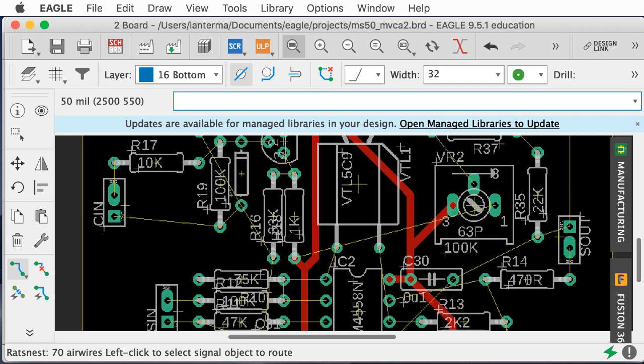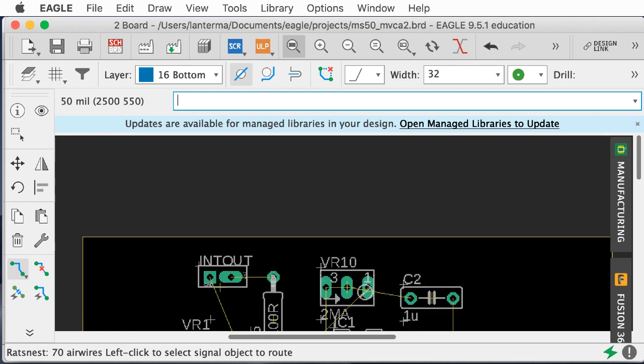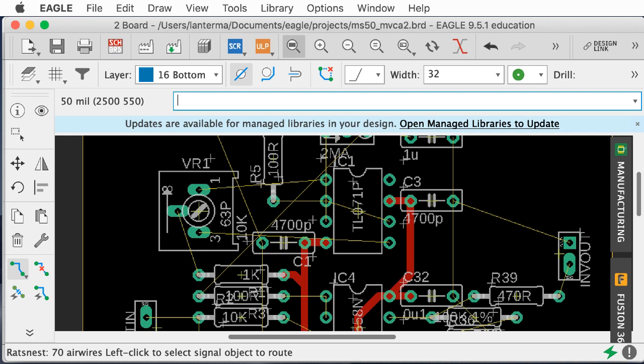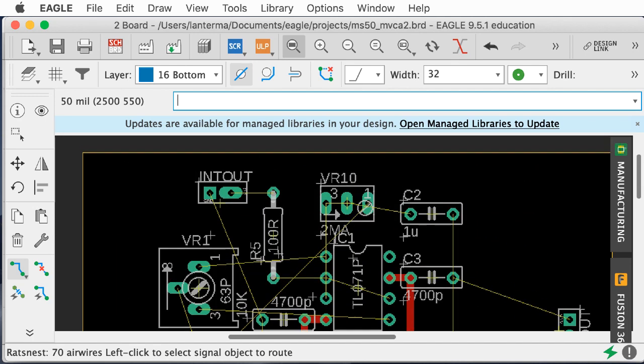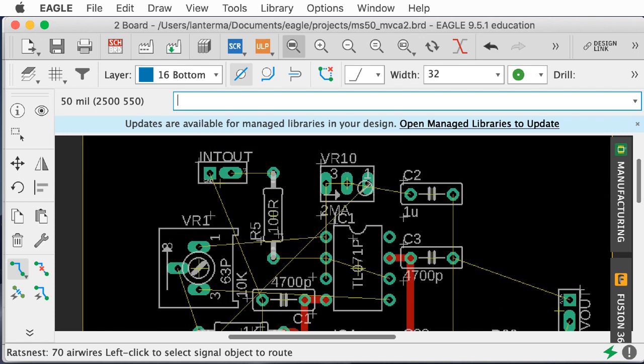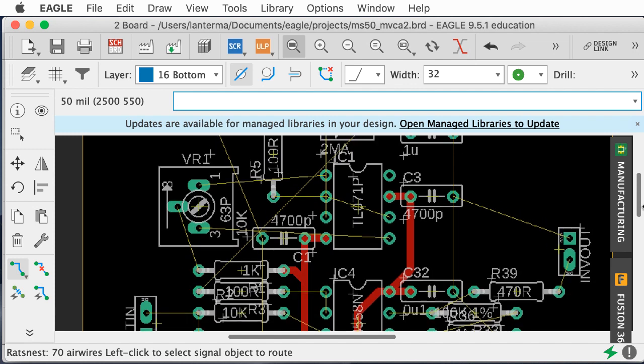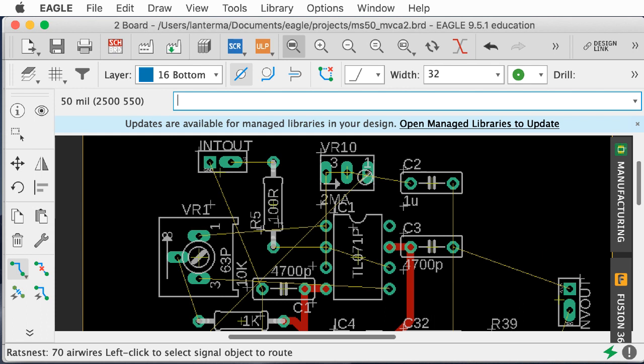Now, in audio circuits, you generally don't see people use ground planes. You see people use ground planes for digital logic, certainly. And I've seen circuits where there's sort of two different sections, where there's like a digital section, an analog section, or maybe there will be different ground planes that are sort of connected at a few choice points or something. But for something like this, I generally do not see people use ground planes. And you can Google that and go to forums and go down a rabbit hole for ages about the pros and cons, about whether, okay, is a ground plane forming an audio ground loop on your PCB?